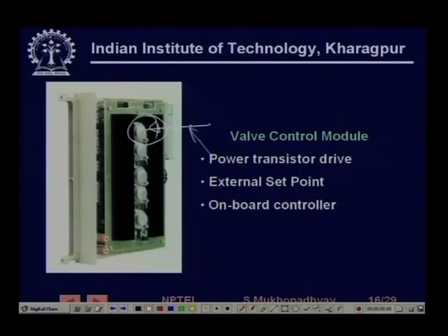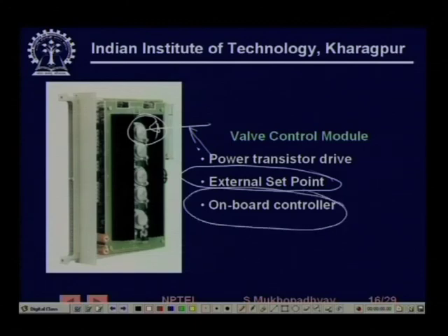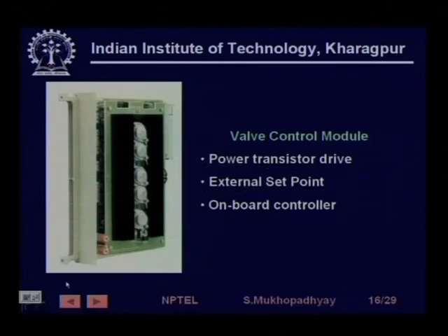So, for that it needs to provide a good amount of current. So, these are the power transistor drives. It takes a set point from outside, so it interfaces to the bus, and the central processor gives it the set point, and it has its own onboard controller. So, this is a typical valve module.